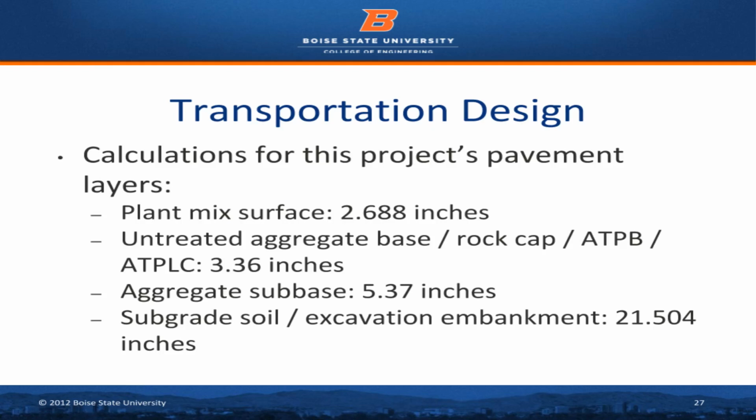And these are the numbers that we came out with for the mix. The plant mix surface was calculated to be 2.68 inches. The aggregate base, 3.36 inches. The sub base, 5.37 inches. Subgrade soil, 21.5 inches. This will provide a strong, flexible parking and driveway.